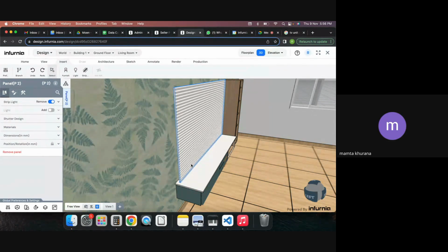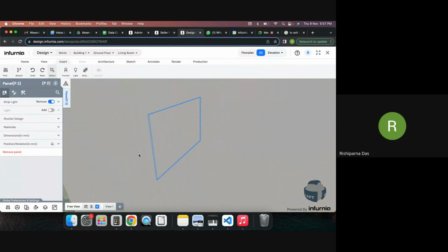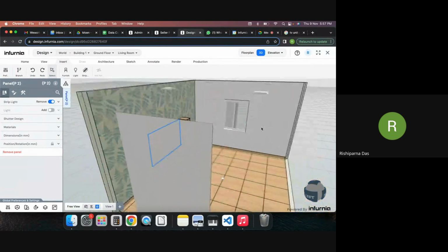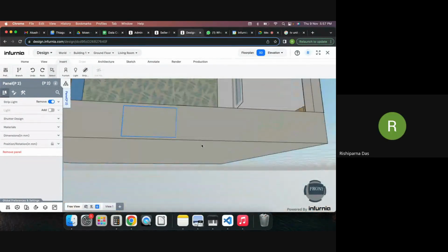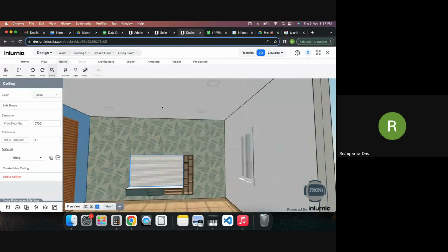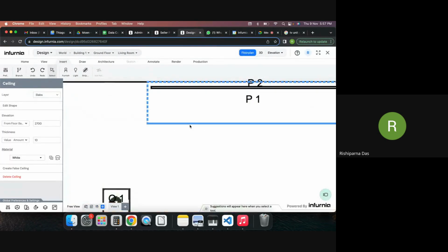Okay, and the same thing we want in the ceiling also, because boxing is needed in the wooden ceiling also. Same way, if we want to put the cove light behind the ceiling, we will need the box which is closed 6 inches behind the main ceiling. Yesterday we were having a discussion around this, that you can actually close the false ceiling also. Say if you look at a false ceiling here, I'm selecting this particular panel here. I'll just remove the lights.